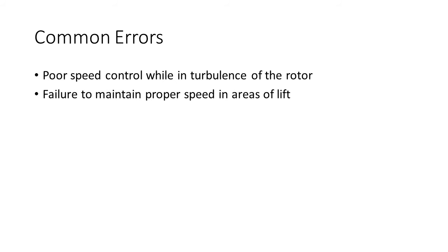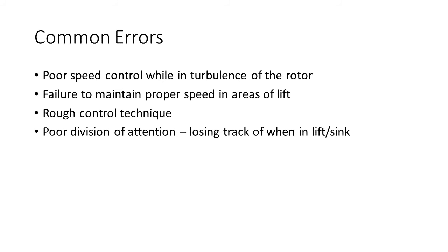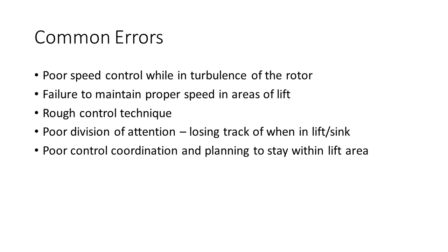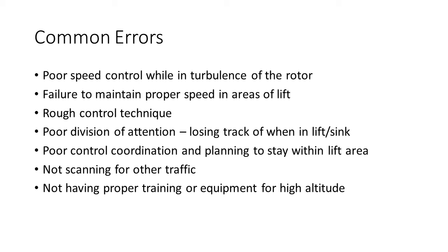Some common errors: poor speed control while in the rotor turbulence, failure to maintain proper speed in areas of lift in order to remain in the lift, rough control technique, poor division of attention, losing track of where you are in the wave pattern, poor control coordination and planning in order to stay in the lift area, not scanning for other traffic, and not having the proper training or equipment for high altitude flights.